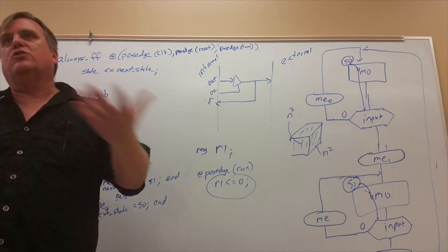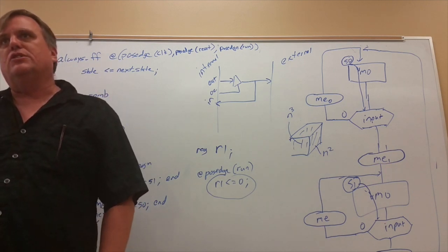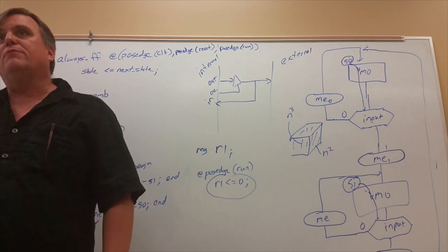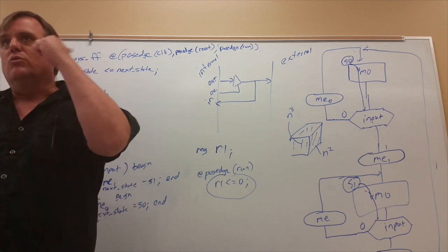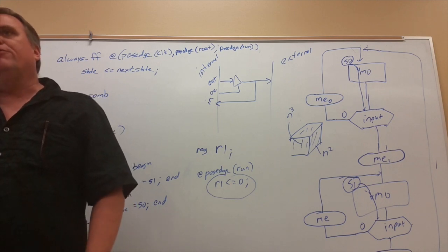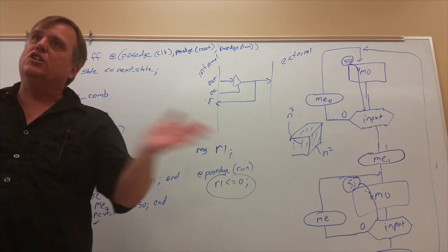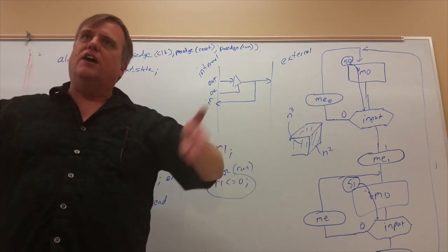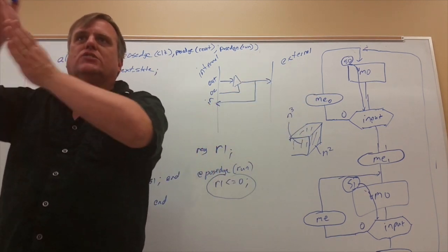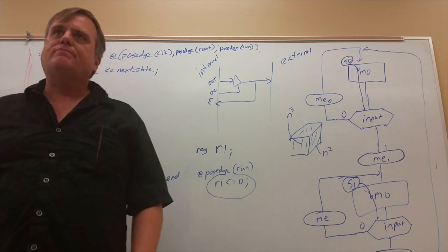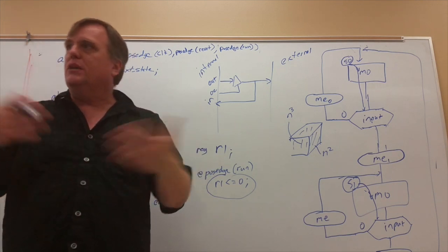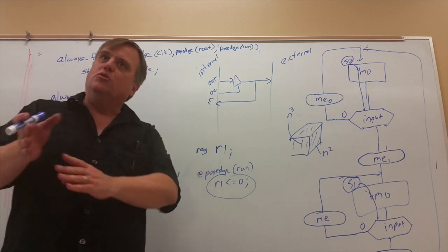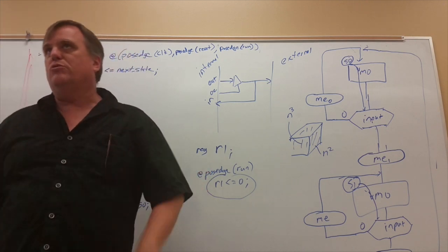So that is the most likely circuit it's going to develop: with that transition to run from the boot time flag, it will set that to 0 just before it starts running, because then that happens just before your program takes over. So it does all the rest of its booting stuff, and at the last possible instant it goes. Because if it did it earlier, somebody else might have messed with it. And you want it to happen a little bit later because you want all the transient voltages to work out.